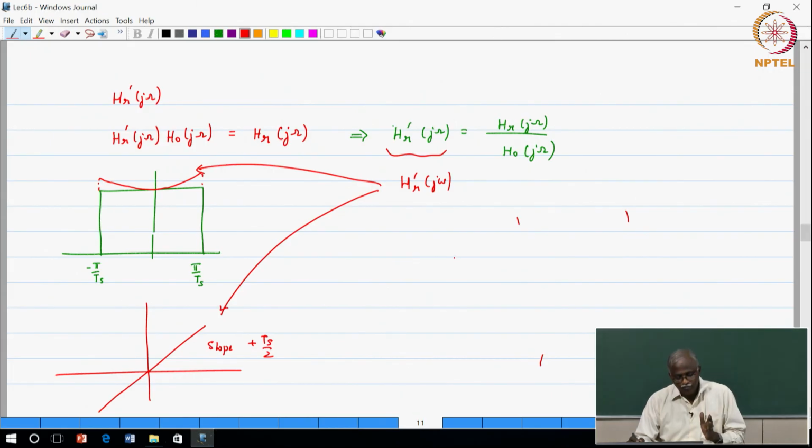Okay. Now, designing an analog filter with these sort of compensations may be difficult. So, that is where once again DSP and multirate DSP can come, because you can do the pre-compensation. Basically, you can compensate for the input signal x of n before it goes into this staircase approximation, so that you can compensate for this. So, the compensation is actually done before the distortion occurs, and you take care of it in the discrete time domain itself.